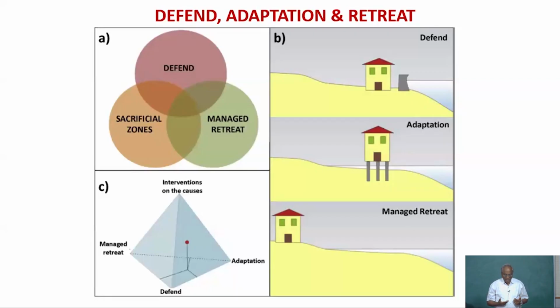That is defend. Many times it may not work. What happens is, this point is going to be very vulnerable. You have a concrete structure standing on sand, and although you will have some apron and some toe protection, you may still have problems. The whole structure can come down.